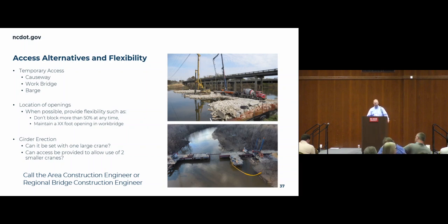So generally, you're looking at a causeway or a work bridge or barge access, right? We have to think through that on every project. Sometimes you don't need temporary access. You can set the beams or the box beams or girders or cored slabs from behind the end bent. But generally, that needs to be thought out on every single project where we're building a bridge.